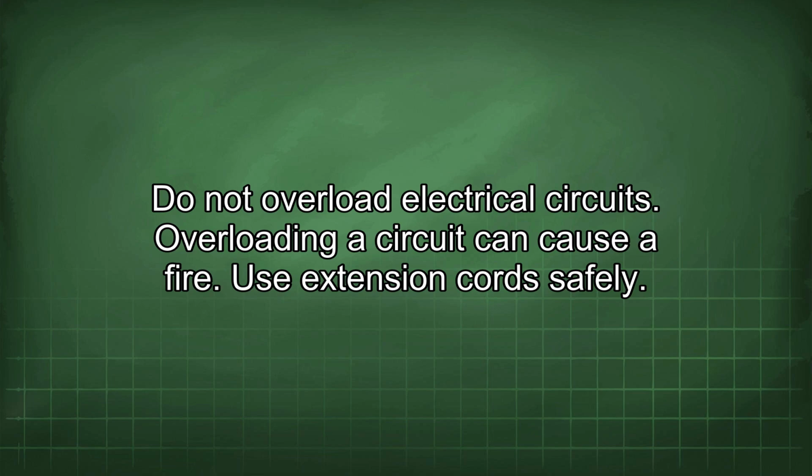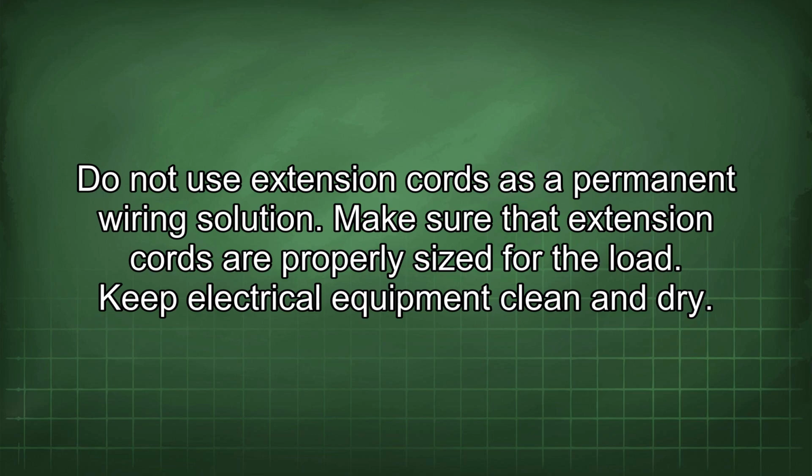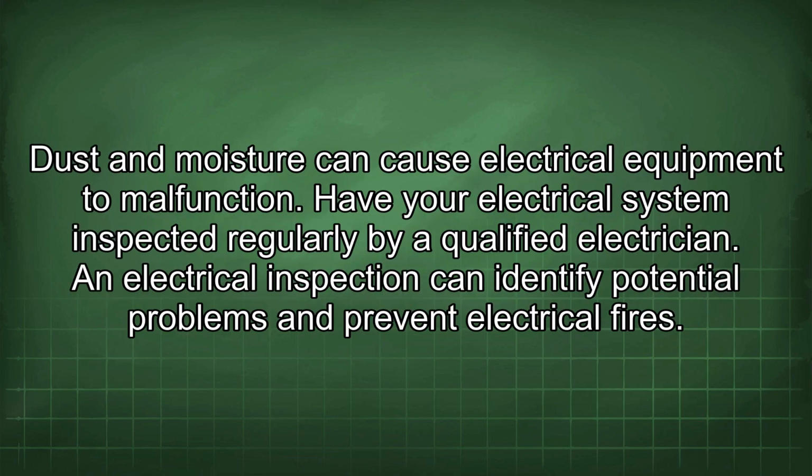Use extension cords safely. Do not use extension cords as a permanent wiring solution. Make sure that extension cords are properly sized for the load. Keep electrical equipment clean and dry. Dust and moisture can cause electrical equipment to malfunction.